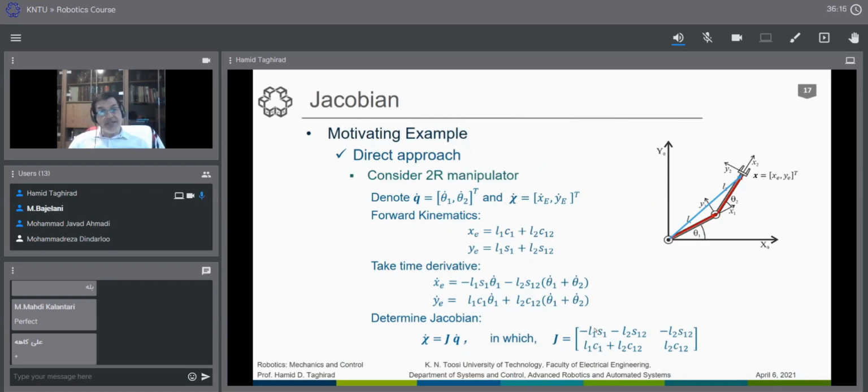Each of these mathematical representations has some physical insight and meaning in the Jacobian. To address that, let me start with changing the frame of representation. This Jacobian has been defined from the base frame, the zero frame.